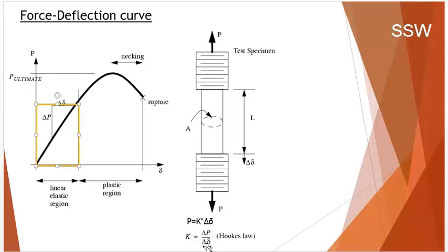divided by delta B. And look carefully, I take the force and divide by the area of the cross section of our specimen. You see, we find the stresses in the cross section. Okay, let's go further. I take this elongation of our specimen and divide it by the whole original length the specimen had before loading. We have a strain.